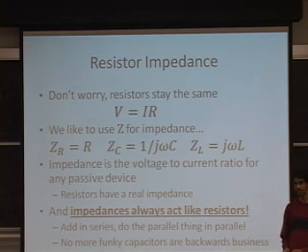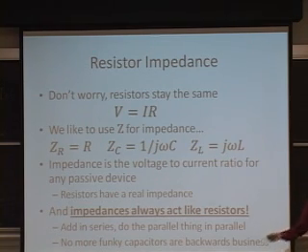The other great thing about impedances is that they always act like resistors. So what this means is that when we introduced capacitors, for example, capacitors in series don't add like resistors in series. You have to do the backwards parallel operation for them. And capacitors in parallel just add, they don't do what resistors do in parallel. However, if we replace these L's and C's and R's with their impedance values, then all of them behave like resistors.